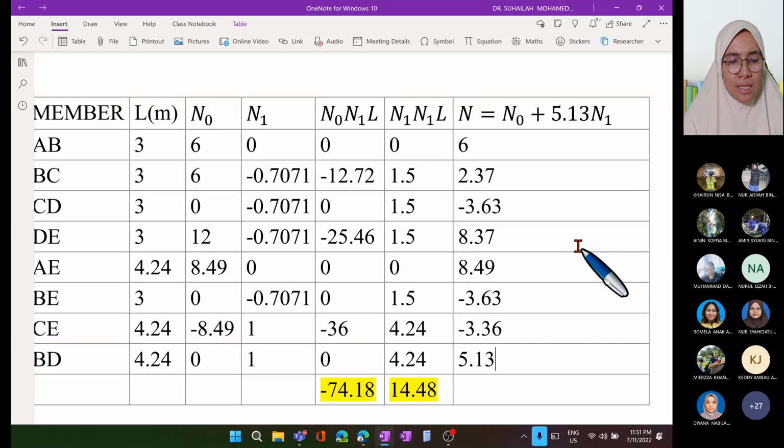In truss analysis, we calculate unknown reaction and member forces. But here I don't show member forces because you will get the same as the example this morning, since the redundant comes from reaction. You will get new reaction in the actual system. So we calculate reaction and member forces. Here, because the redundant comes from member forces, you will get back the same reaction like the primary system, and member forces you will get all new values. So read the question carefully.